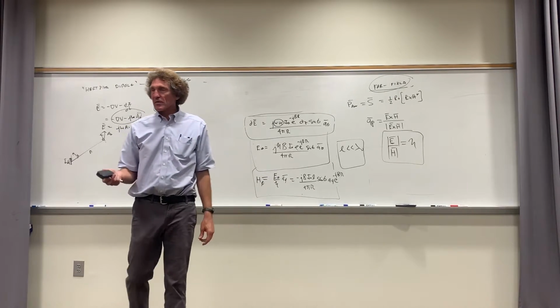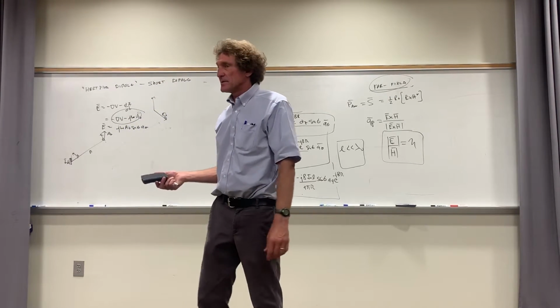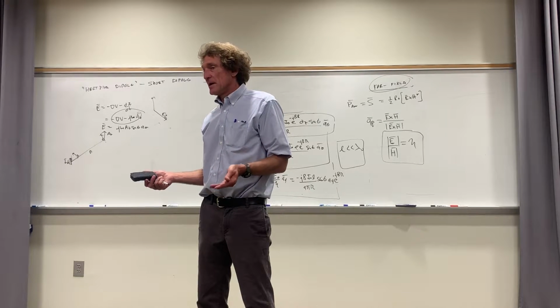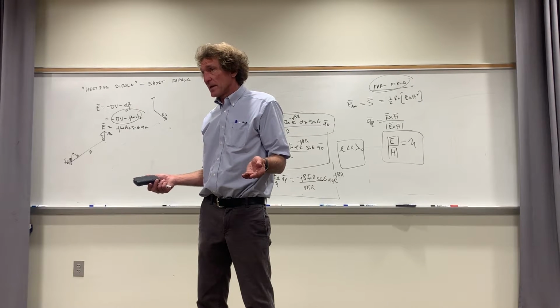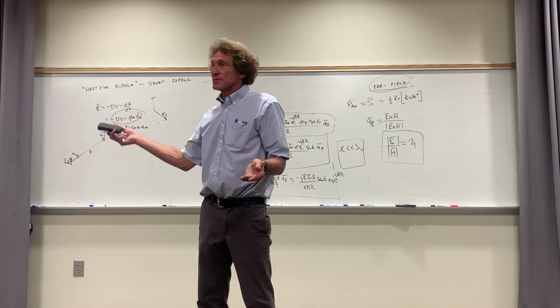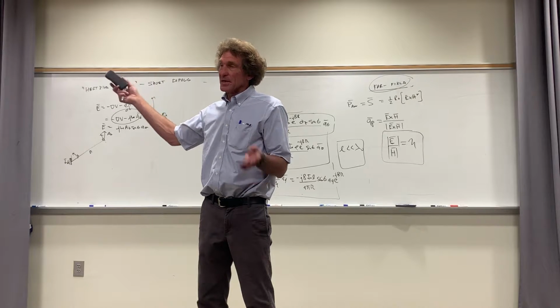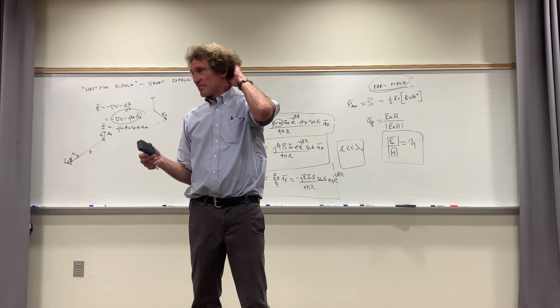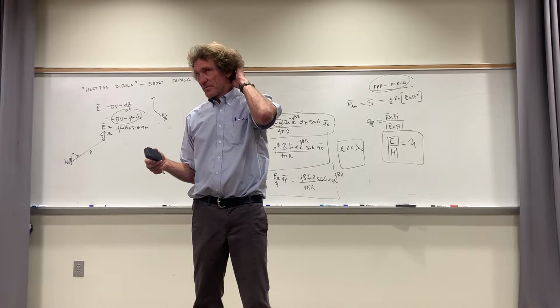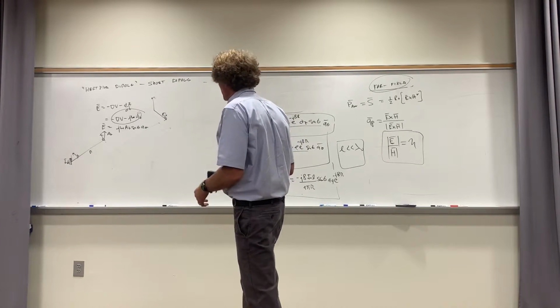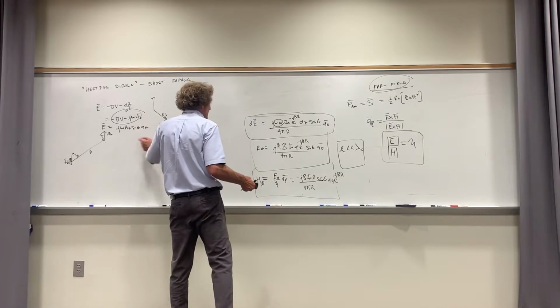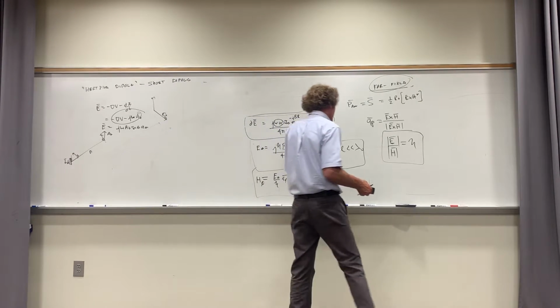You go through the entire curl. If you calculate what A is, then take the curl of A to get B, divide that by mu. Now you have H, and take the curl of H again, then you will get j omega epsilon times E, and then you divide by j omega epsilon. And the j's basically get rid of that negative sign, but I really don't want to do this. This right here is right, and it should be a positive. You're right. I'm sorry about that.